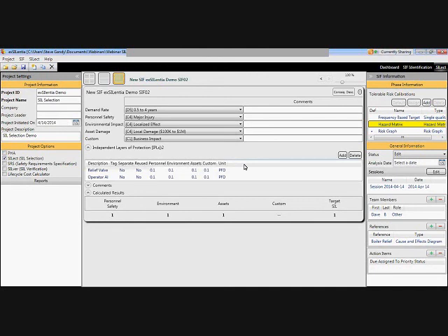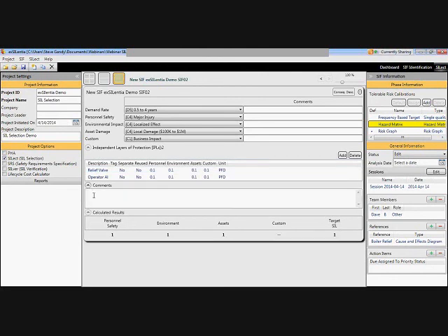So IPLs will have an impact. You can also add comments. So any notes or comments you want to make, and you can build up several layers, independent layers of protection if you have them. You can put comments in here. Here we've said localized effect, but if you were to say there was a major effect on the environmental, now you've pushed it back up to SIL 2.